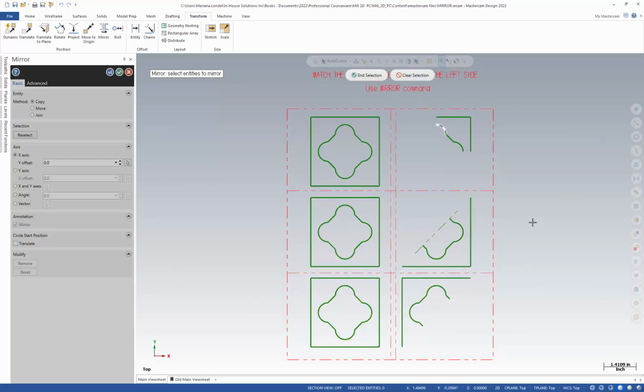Going to clear selection. Sometimes, because the system automatically snaps to one entity selection, it is harder to select the geometry using window. To force a window selection, you can also hold down the Control key and then release, and then just drag the cursor around the shape that you want to include in the window.